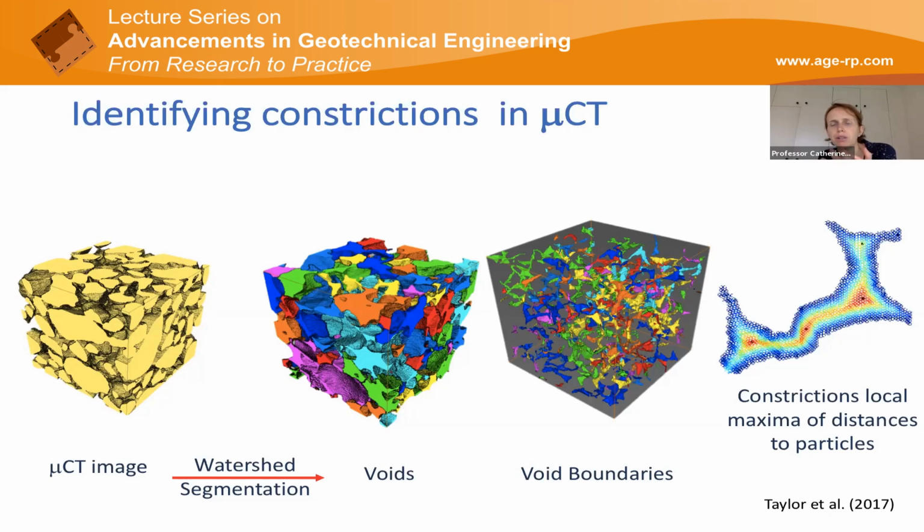If you've got particles that are angular and bumpy, you will have more contacts per particle than you would if they're perfectly smooth, because if you look at my knuckles, I can interact my knuckles at 4 points because they're rough, whereas if I take these 2 cylinders on my desk, they can only interact at 1 point. And that increased coordination number brings in resistance to rotation between the particles, and that increases strength. And whether you need to do that depends on the particular question you're asking.